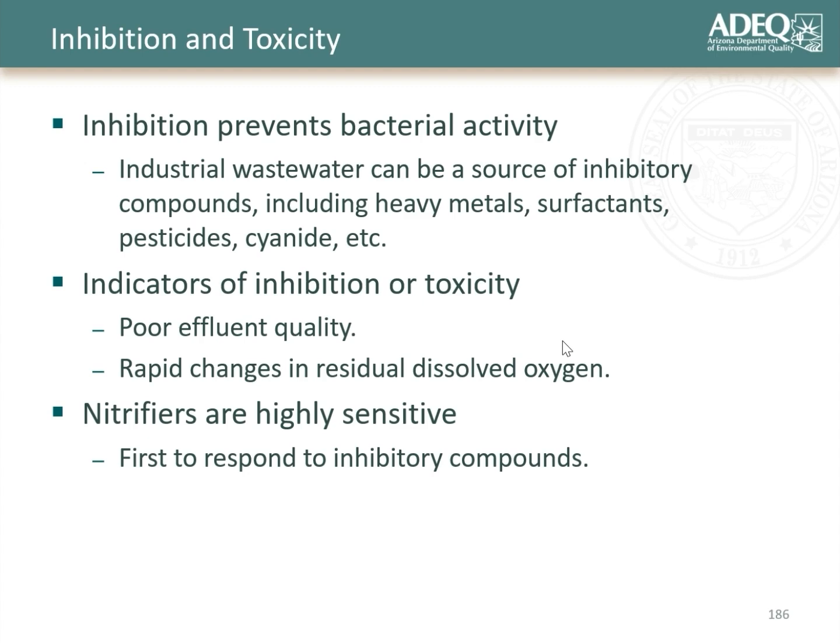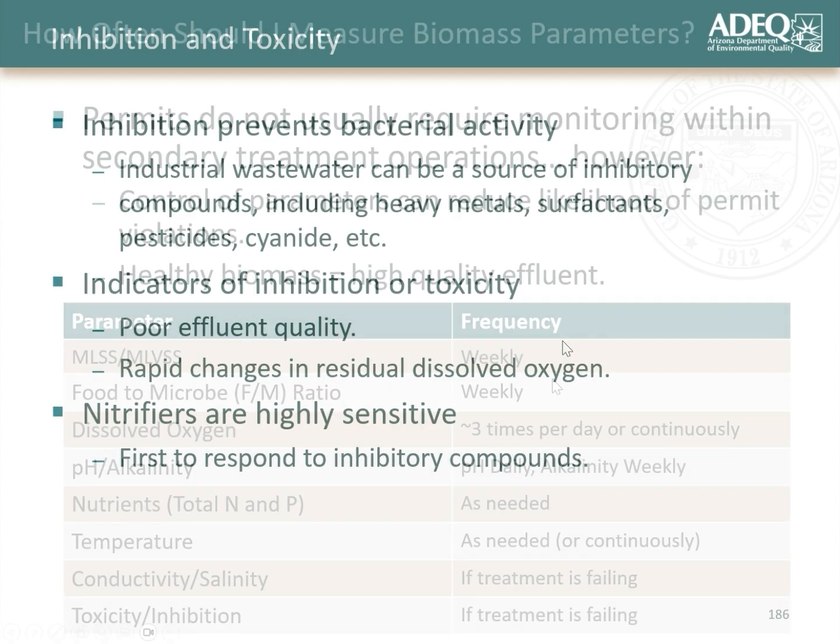Also, one thing to note is nitrifiers are definitely highly sensitive. So if you happen to have an ammonia or total nitrogen limit for your system, be really responsive and watch the nitrifying population to make sure they're protected as well, because they are frequently the first population to go out in systems. So another important thing to think about.